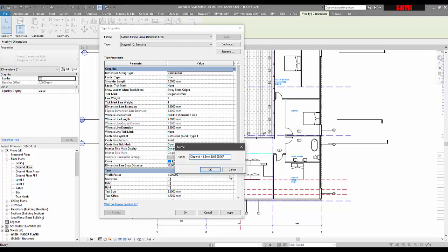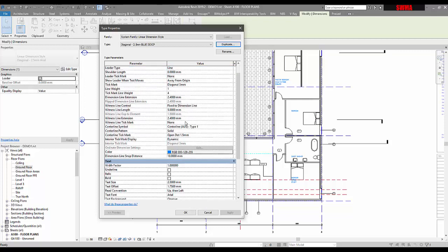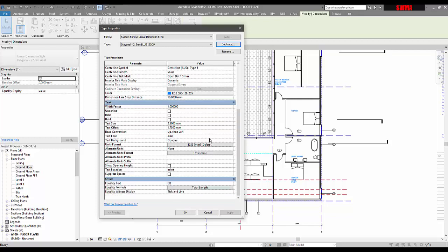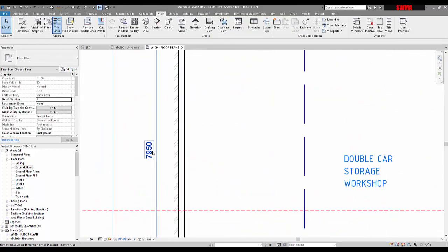So CP, go OK, and then change the Arial. So where is it? Arial. Change the text from Arial text font to SCP, and bold again, and I'll just leave everything on a standard and go OK, and that's adjusted that one there.